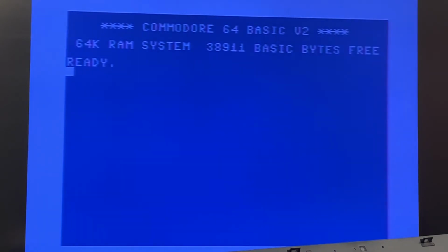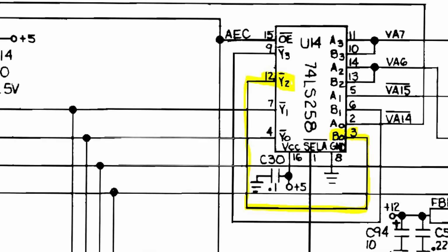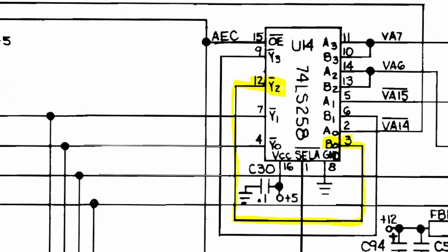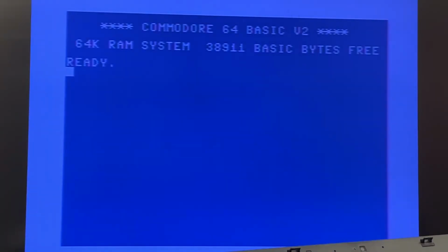And to be honest, if I'm looking at the schematics, that line is just an output going into an input. It doesn't go anywhere else. So I would definitely think that chip has a problem. And by the way, it happens to be a MOS chip, which I understand are not very reliable. So let me do a few more tests on this chip before I go ahead and replace the whole thing.